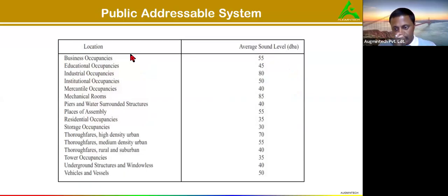That should be maintained. In the case of a fire alarm system, once you have installed all the sounders or flashes, we test the decibel level with the help of a decibel meter. Carry the decibel meter in your hand, switch it on, activate that particular sounder or speaker, and check the decibels, with the door closed and door open. You'll get different decibel values, and there is a normal range we have to maintain. If it is above or below that, both are issues. Above, it would be irritating for the ears, and below, we may not be able to hear it clearly.